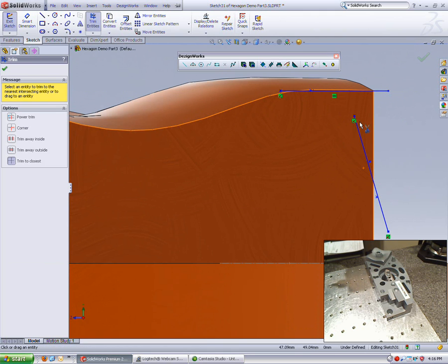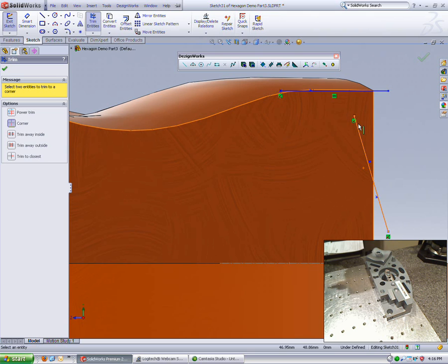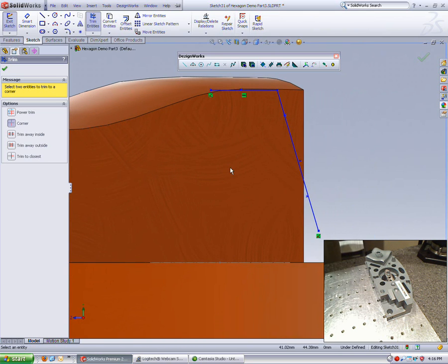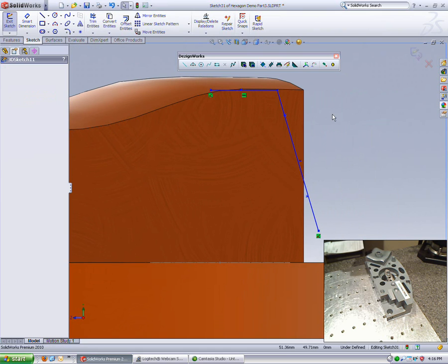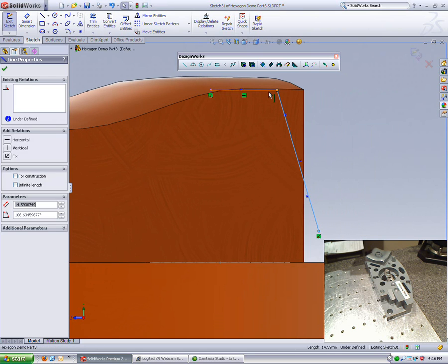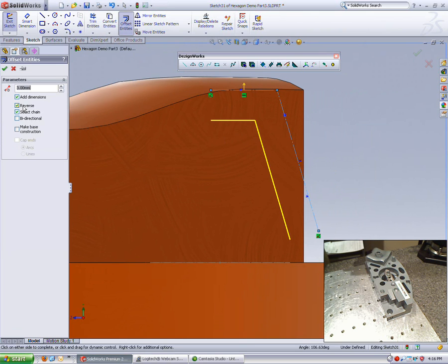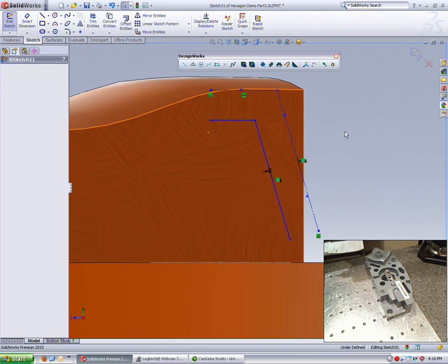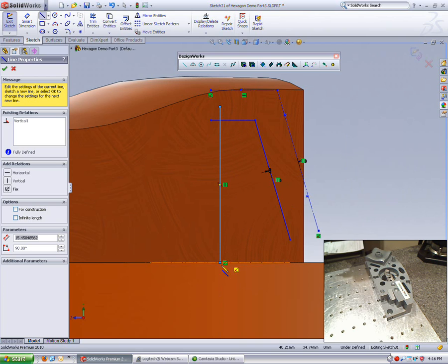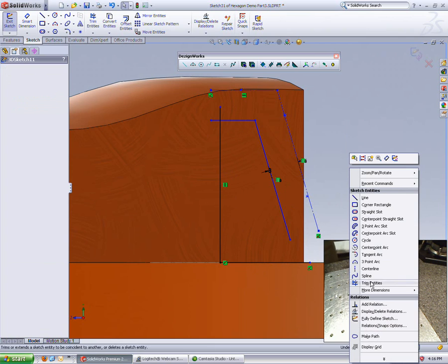What we'll be able to do then is use this to actually get a cross section through this circular shape. Inside of Dezignworks, sometimes you don't automatically compensate, and so here what we're doing is we're actually doing our compensation for ourselves by offsetting this geometry right inside of our sketch. So we've just offset half the diameter of our probe,